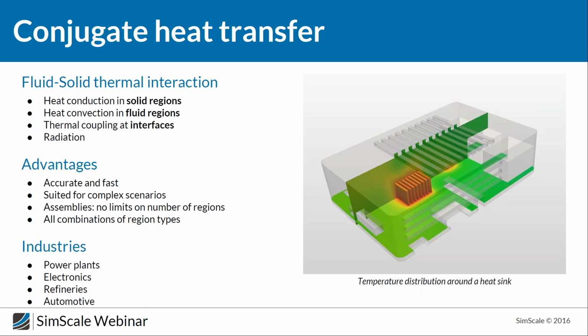So now we have an understanding of what this type of simulation offers on top of the existing heat transfer analysis types that we have. A few of the advantages are its accuracy and its speed. If you want to do simulations of the same complexity that you typically have to simulate with a conjugate heat transfer simulation, it is extremely difficult to achieve those levels of speed because it's a coupled simulation, or accuracy because it really considers the simulated data and not some more or less simple boundary condition. It's very difficult to reach those two levels of accuracy and speed.